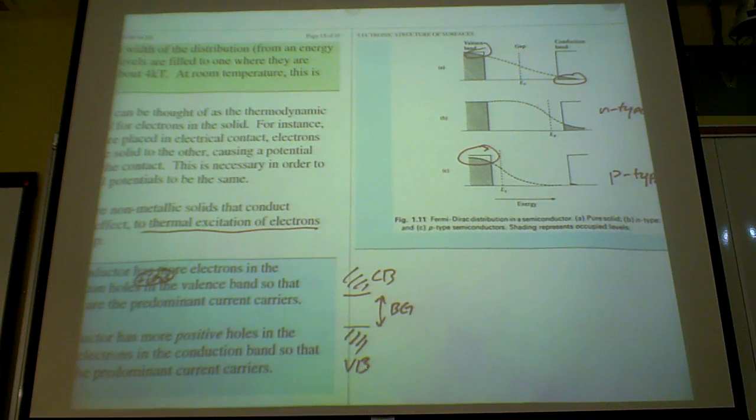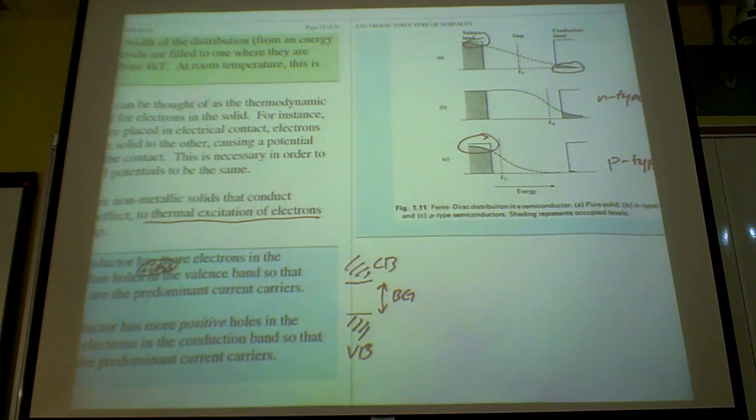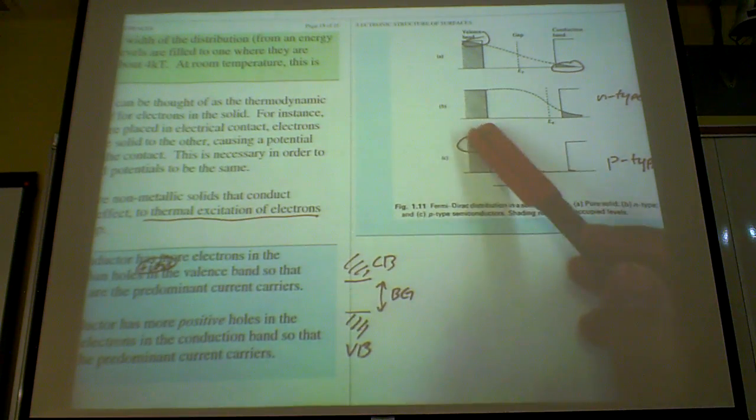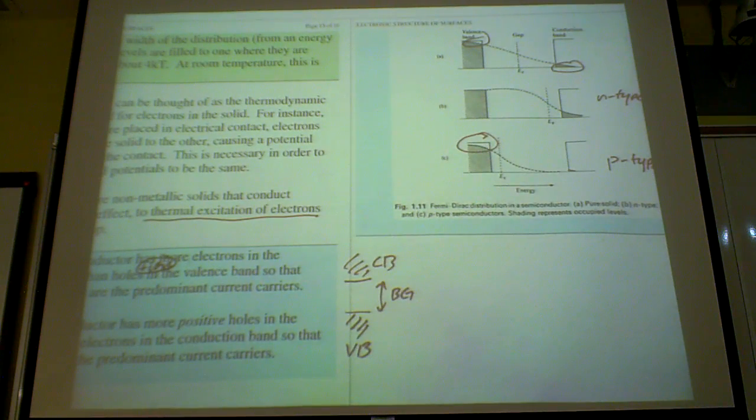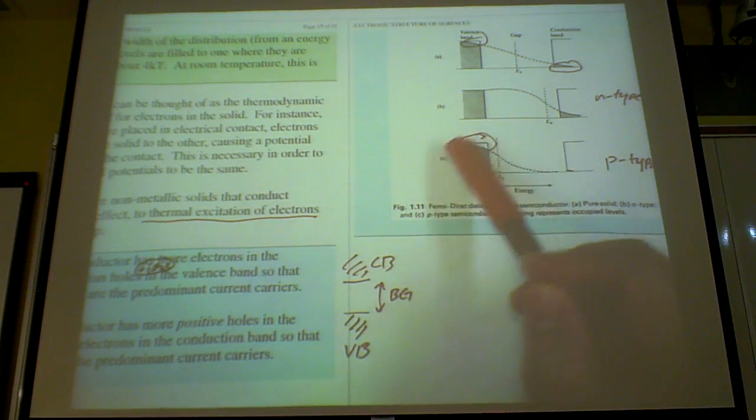Okay. Or you can dope it in a different way. You can dope it with some material that are poor in electrons, more electron deficient. So like boron, for example. You dope here with phosphor, for example, then you have N-type. With boron you get P-type or positive type, because boron has less electron than silicon. So in fact, you create a deficiency, less electron inside your bulk, the majority of the bulk of the silicon that you have. So you got more positive hole in here.